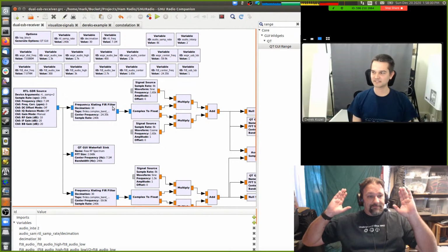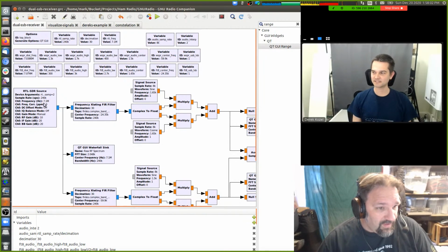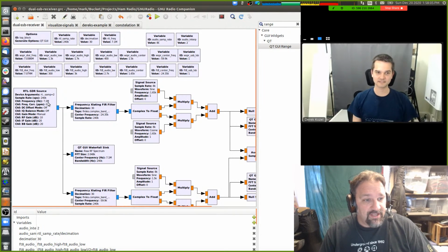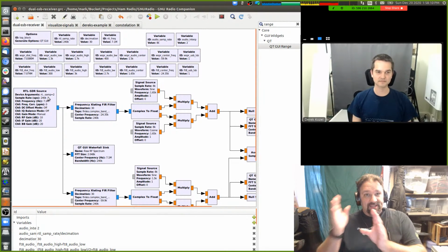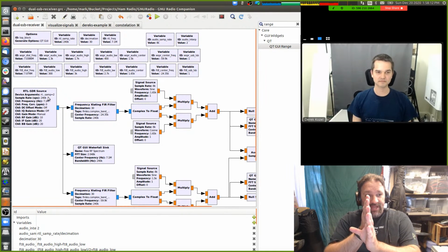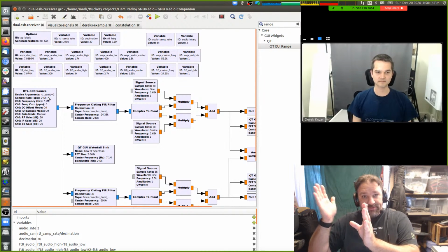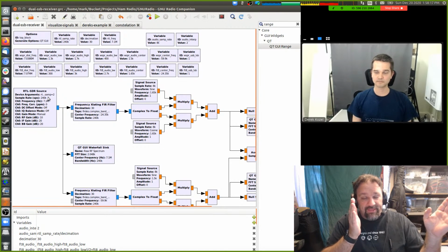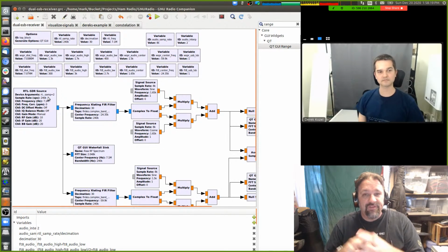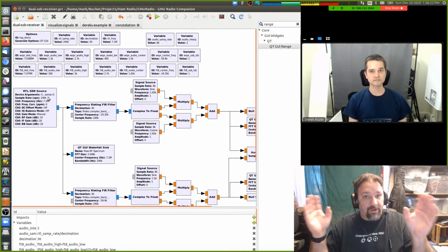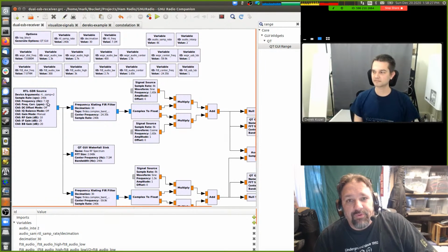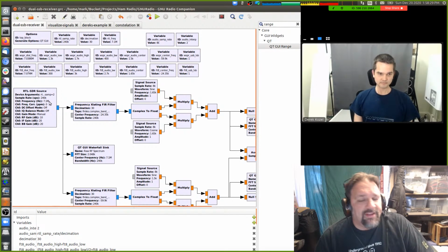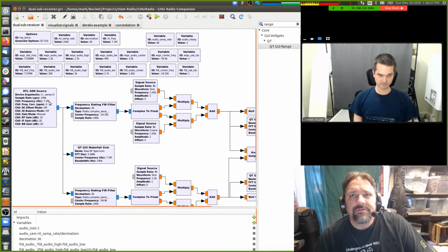Basically, I've got my RTL centered at 7.1 megahertz, and it is sampling 240 kilohertz, which means from 7.1 it goes up by half of that, so to 120,000, and down by 120,000. So the idea being that this was a convenient sample rate to grab most of the 40 meter band, right? And so it's 6.98 up to 7.24, 6.96 to 7.24.